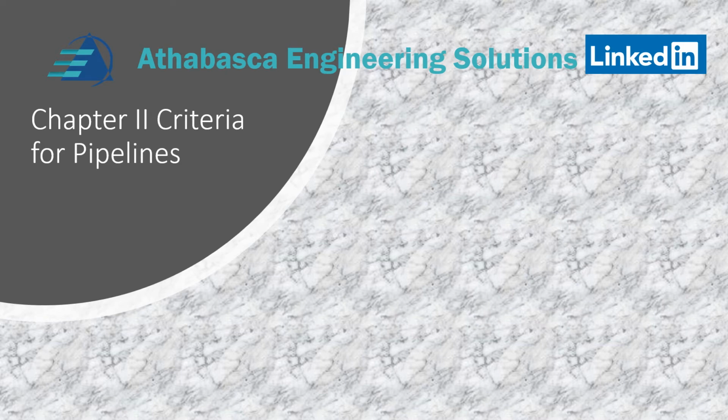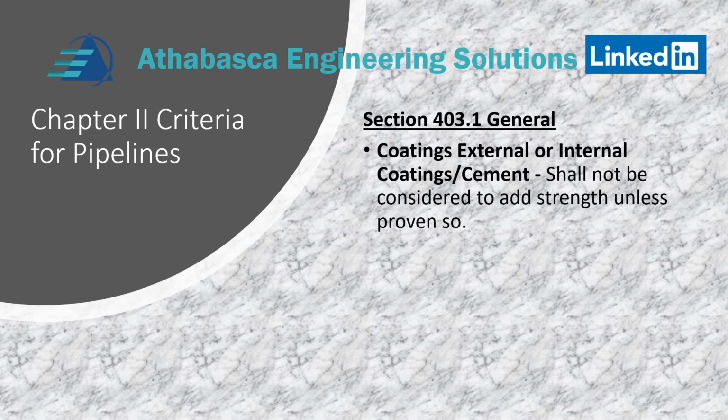Now here are the last 2 points to go over. It's about coatings, external or internal coatings in cement. They say that you should not use them to add strength to your part unless you can prove so. I've experienced this problem considerably over the years with liners for wear and so on. And basically what I discovered was it adds more to the stiffness of the component and it reduces the flexibility of the component. And in my opinion, that should be considered.